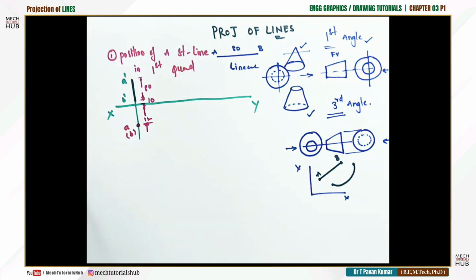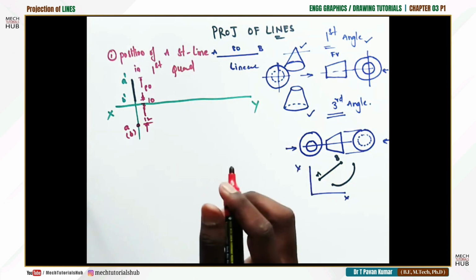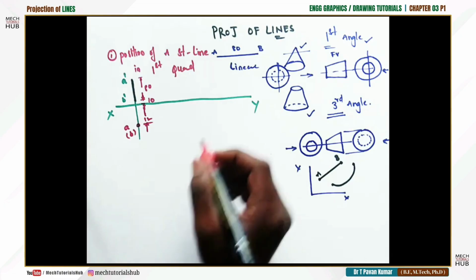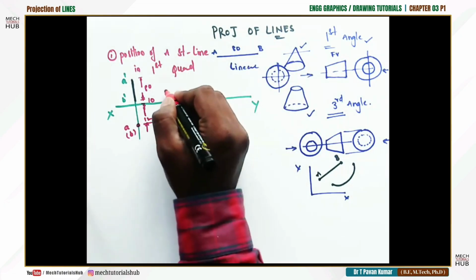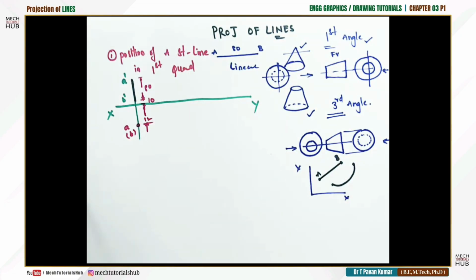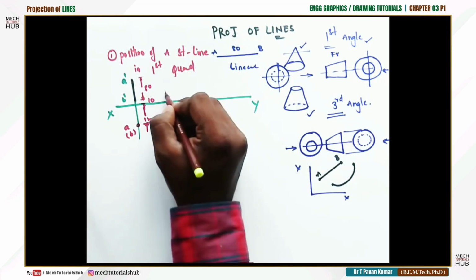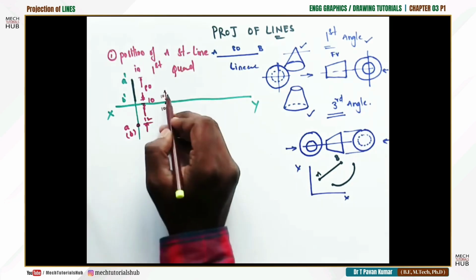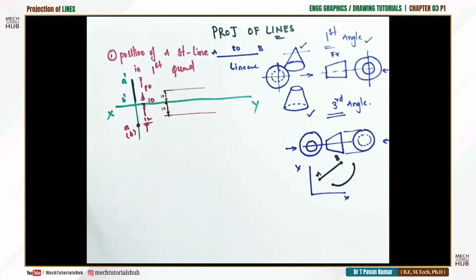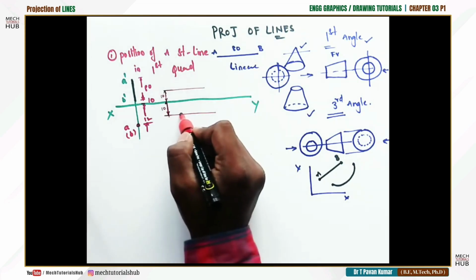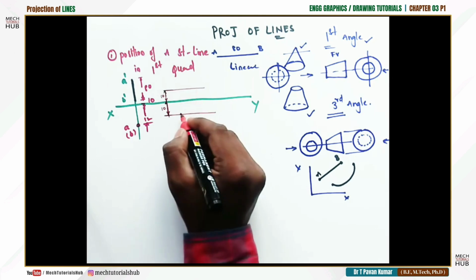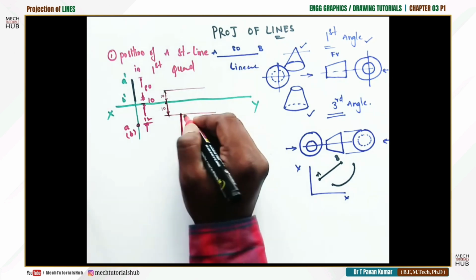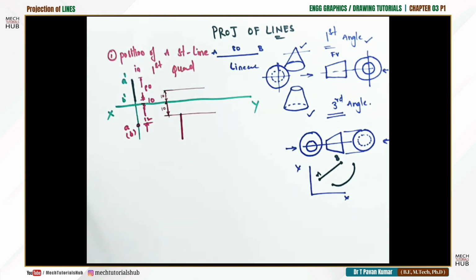Have a look. As both the planes are maintaining an offset distance of 10 mm with respect to that particular line AB of 80 mm length, what I try to do is I'll just draw a simple line here somewhere. Okay, I'll consider this distance as 10 mm, this distance also 10 mm. Then I'll try to draw one locus. This is the right procedure actually. Fine. So where I could see the true length of the line from the top. So 10 mm away, try to make a point. From here with the help of the drafter, draw a straight line of 80 mm, which all depends on the position again.